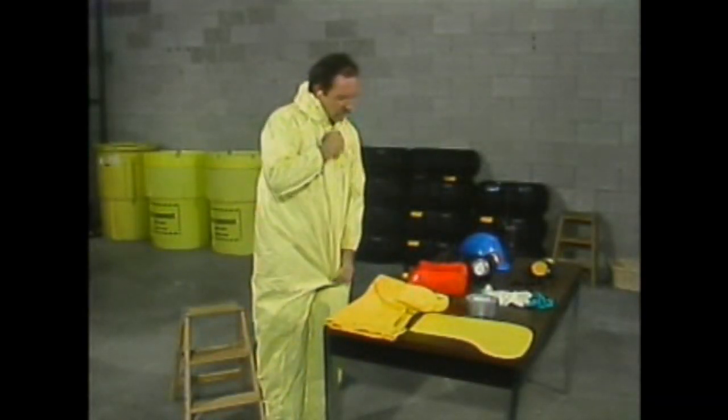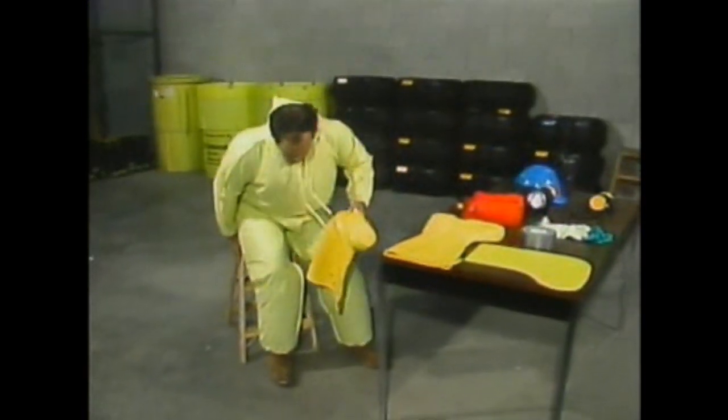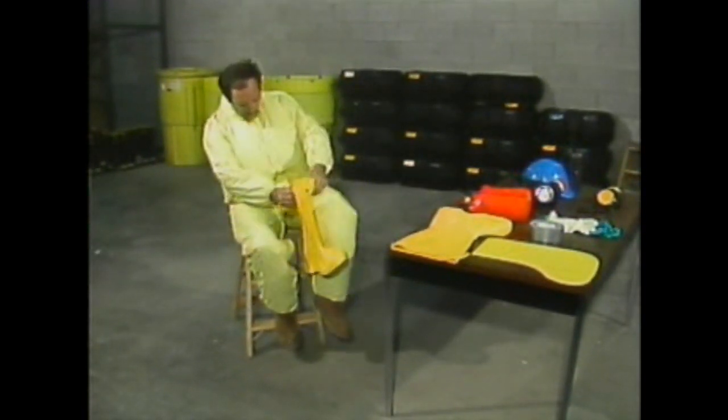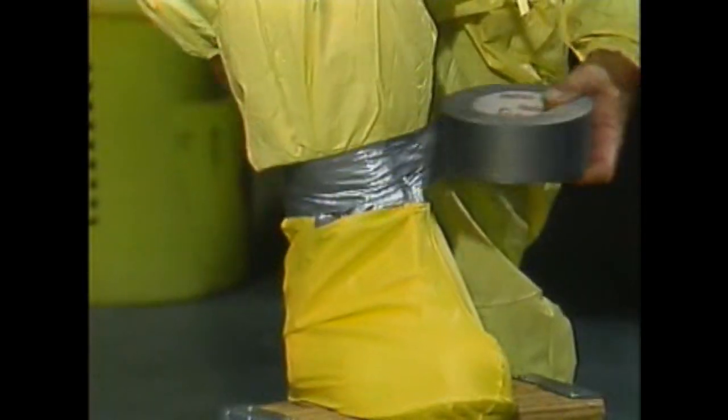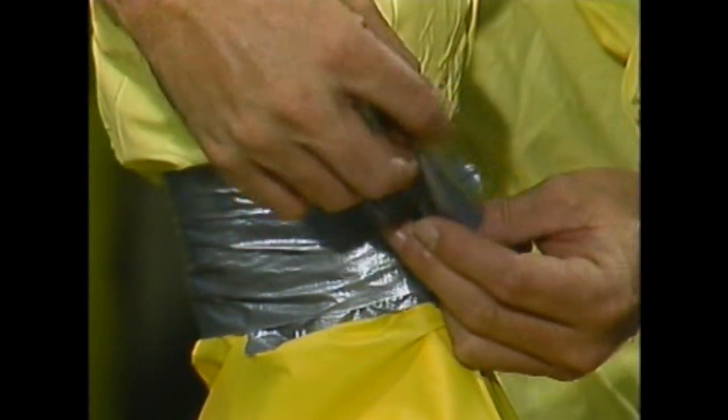Along with a chemical suit, chemical boots are frequently worn over steel-toed boots. The type of boot depends on the type of contamination. Disposable boots protect your boots and your skin against exposure to dirt, dusts, and other contamination, while rubberized or chemical boots protect against exposure to liquid contamination. To prevent chemicals from entering the boot, your pant legs should be outside the boots and sealed with tape or elastic. If tape is used to create the seal, make a tab at the end of the tape. The tab will help you get the tape off when your work is done.